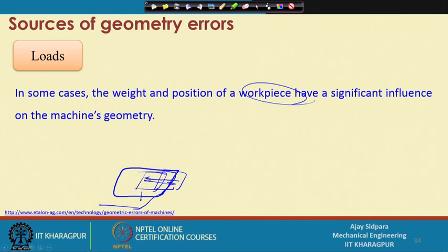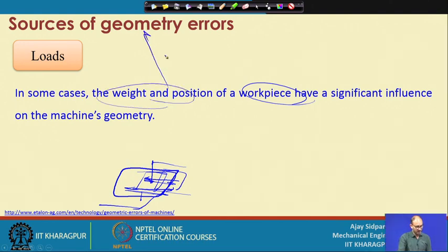If you do this hundreds of times, there is a chance of wear of this particular component, and sometimes you are sliding, sometimes we are just locating it at the top and then dropping it down. At that time it will create an impact, and if you are sliding, it will create a scratch. So, after a long time, if you continue in such a way, you end up with some type of problem in the geometric error. So, this will actually destabilize the whole structural loop, and that will create a problem when you do the actual machining operation.